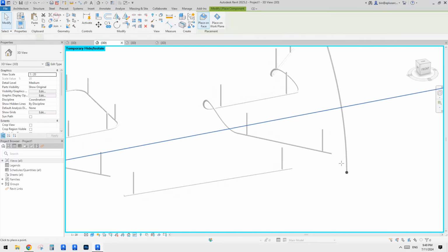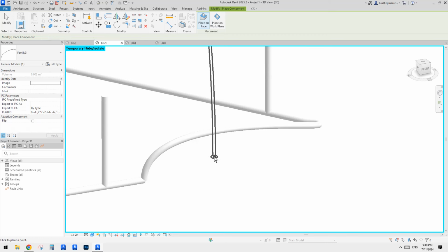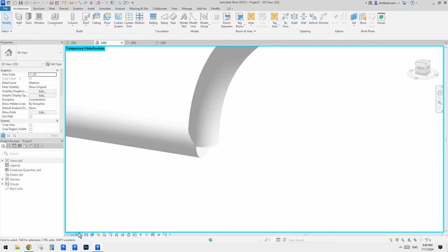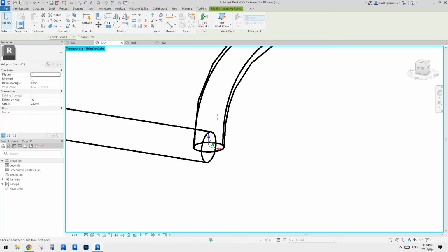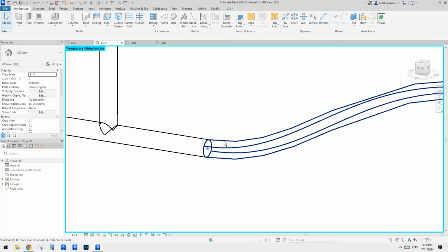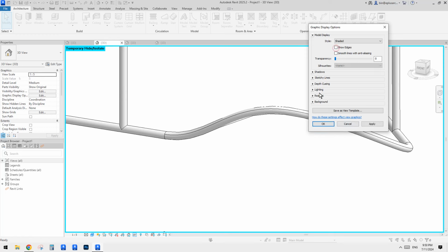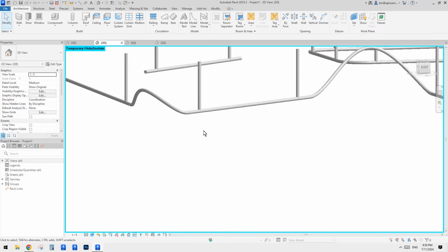Let's do another one. Component, SC, escape. Oh, looks like this point was placed onto a wrong spot. So let me change the scale a little bit. You can type WF if you find it hard to pick this point, and pick new host, type SC. Yeah, that's it. Type SD to bring back, GD to turn off that show edge, maybe turn the lighting down a little bit. Okay, so this is it.